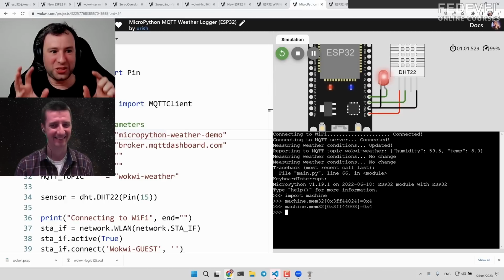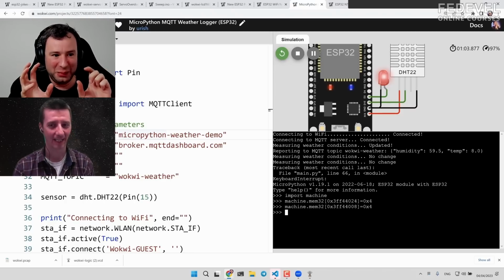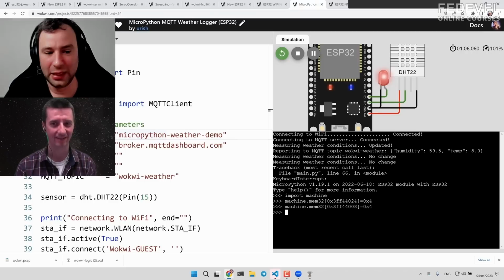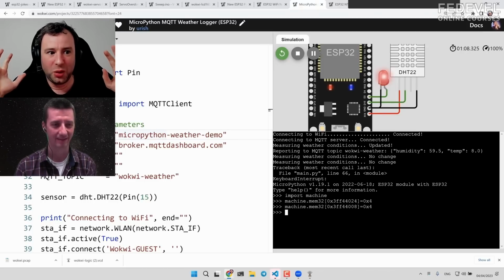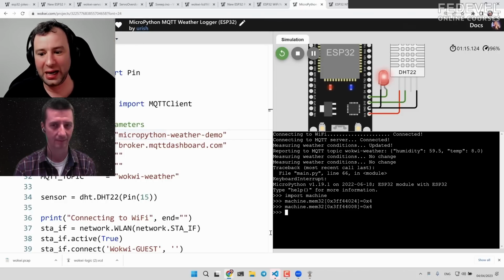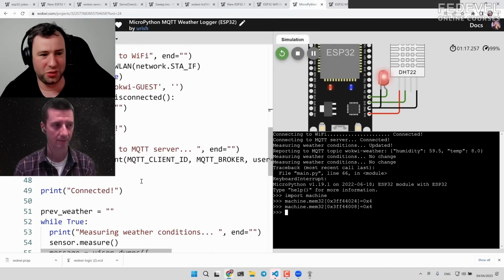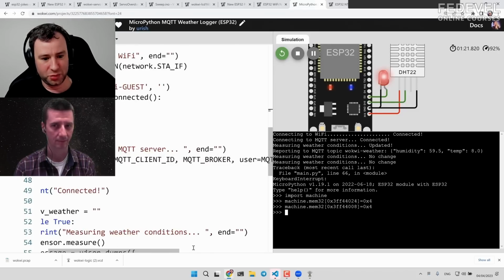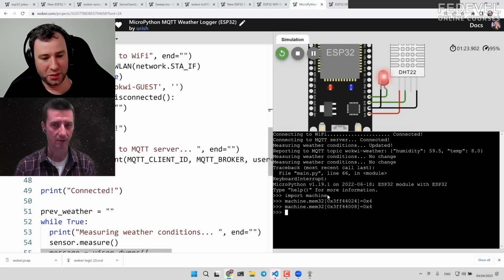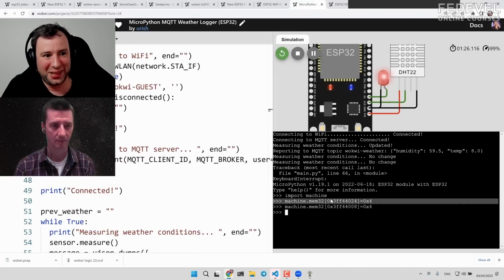So yeah, you can actually manipulate on a very low level. The simulator doesn't really know what it's simulating. It's just running instructions. So even if you call the high-level API of MicroPython to toggle the LED, or of Arduino, eventually this translates down to these write instructions. Exactly. So this also means that you can just send these instructions directly or write assembly code in Arduino,